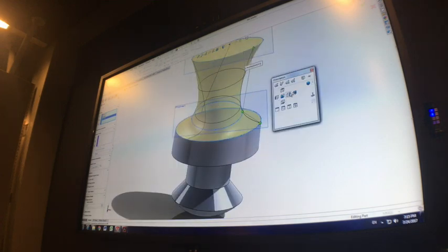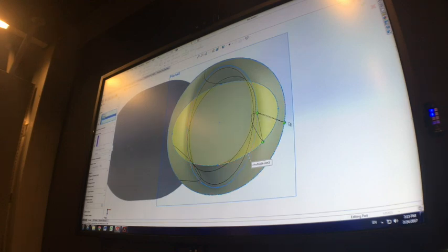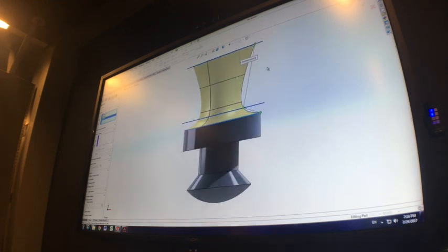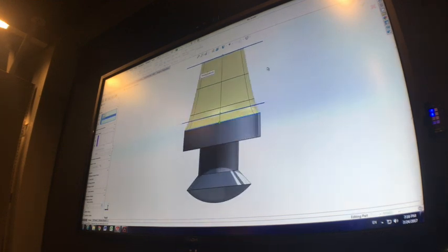So if we go to the top view, we can see how they're a bit twisted. Just bring them around so that those control points are all in line, either horizontally or vertically. And now you can see the mesh preview, it's much more symmetrical around those control points. So see that curve at the top and around the bottom. And then when we have a look from the front view, we can see that's pretty well balanced front and back.